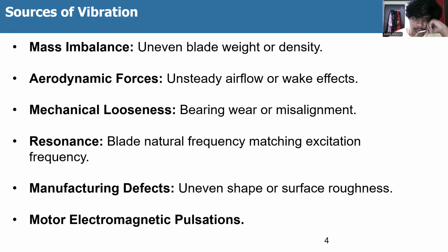Sources of vibration. Mass imbalance means uneven blade weight or density. Aerodynamic forces means unsteady airflow or wake effects. Mechanical looseness means bearing wear or misalignment.